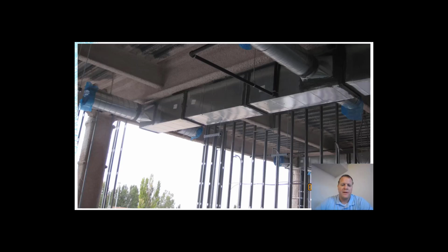There's some debate, and folks feel differently about whether you should try and block out holes in stud walls for ductwork to pass or whether you should just let the framing go up. But I think that's something important to think about as you're talking about construction sequence and construction coordination. I've seen folks even decide that they're going to put the ductwork in and then frame around the ductwork, which I think has its merits. I like the sequence, it's good. That doesn't always work, but it is a good strategy sometimes.